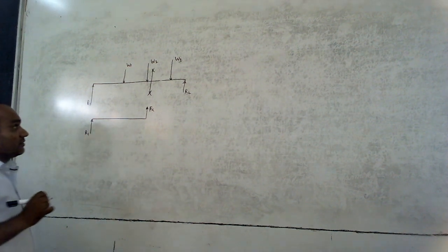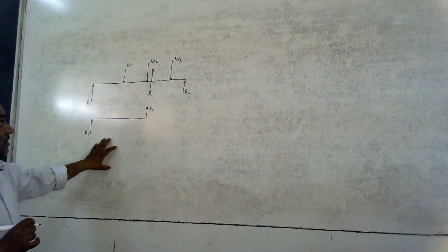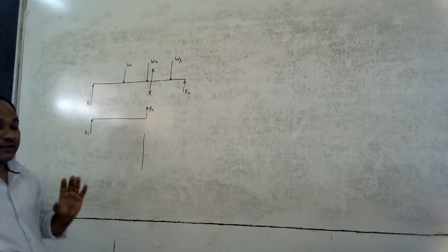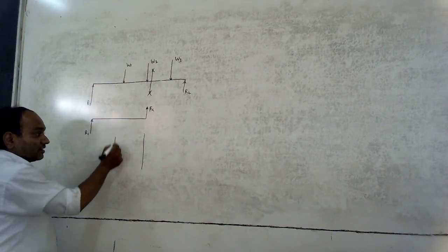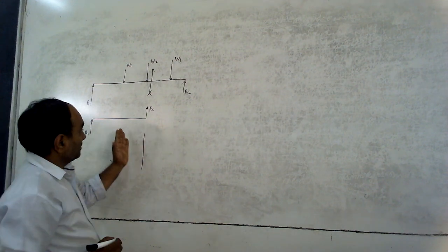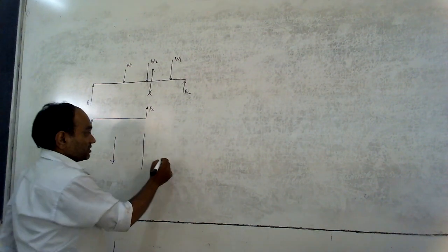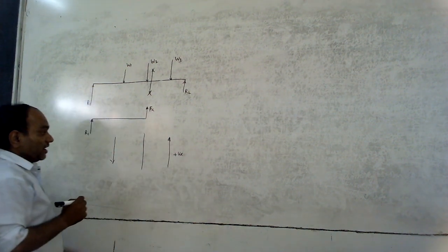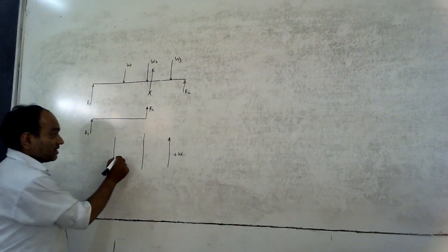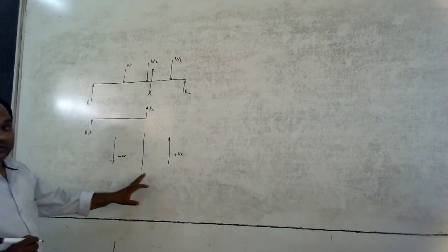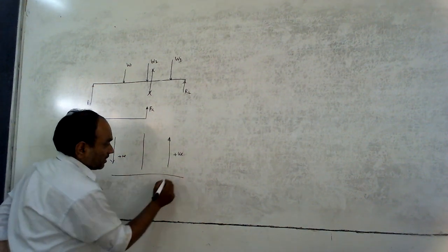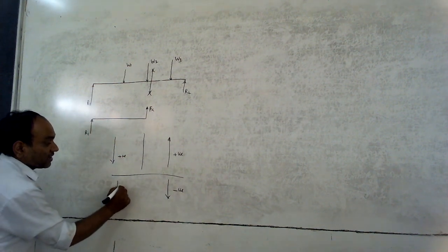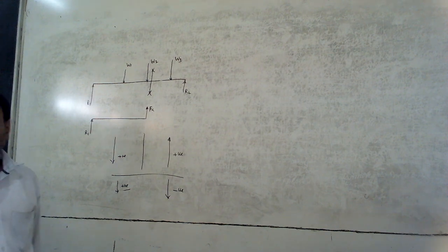Now the sign convention of this shear force. The left side of this section is considered positive if the shear force is downward, and on the right side of this section upward forces are considered positive. Upward forces are taken as positive forces on the right, and downward force is taken as positive on the left. Upward forces on the left are negative. So please write it down.